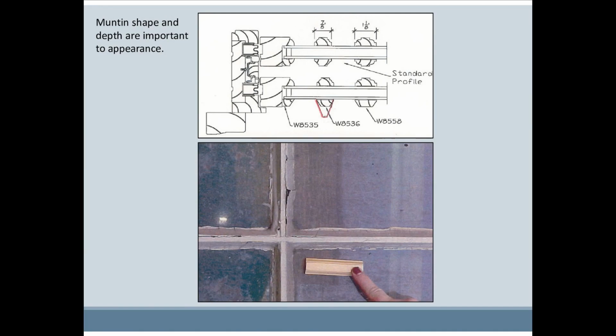Large, thick, historic sash often had a deep putty line. Even if the muntin width can be correctly matched, the appearance will be quite different if the depth is reduced. The whole assembly can appear flat and false in comparison to the original.